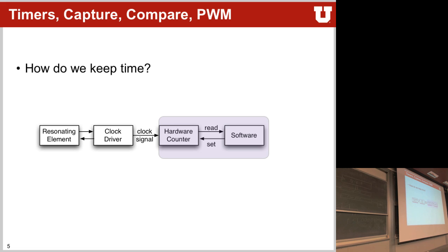Right? So if you write this now in CCR1, what will happen is when the count reaches that particular value here, it will flip the GPIO. When it reaches this one here and resets, it will set it back to 0. It will keep counting back up to 80%. It will flip it again, high, gets low again, gets high again, gets low again.